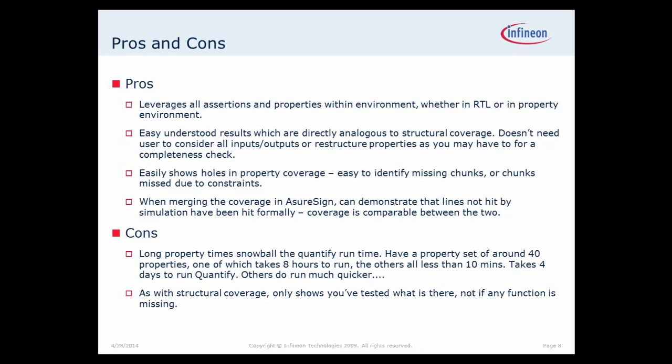And then you have one coverage database with all of the coverage data in there, with simulation paths effectively down to showing where your hierarchy is and where your functional coverage bins are. You've got assertion path files for the assertions themselves, and also in case here structural coverage. So it translates the code you physically executed into structural coverage, so that's available there too. I think there's a question coming from Cambridge. But yeah, if you want more information about AsureSign, then you can always ask.